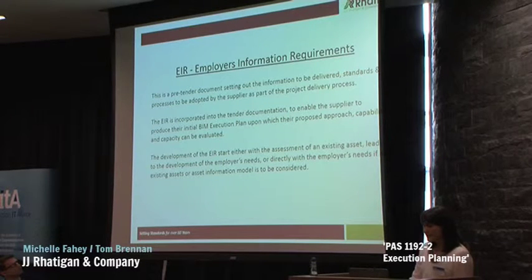So the EIR is the pre-tender document setting out the information to be delivered, the standards and the processes to be adopted by the supplier as part of the project development process. The EIR is incorporated into the tender documents to enable the supplier to produce their initial BIM execution plan, from which their proposed approach, capabilities and capacities can be executed. The development of the EIR starts either with the assessment of existing assets, leading to the development of the employer's needs, or directly to the employer's needs if no existing assets or asset information model is to be considered.